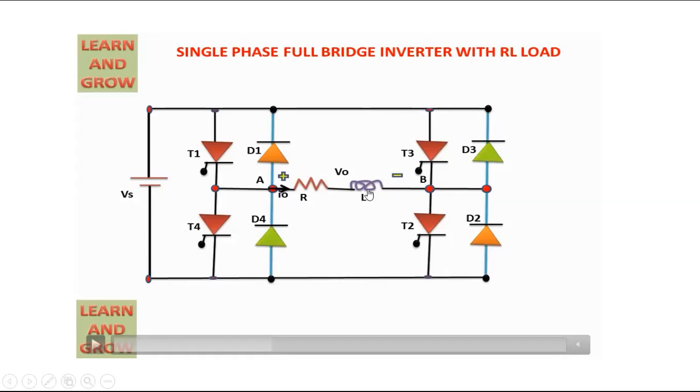So now when inductor de-energizes, the de-energizing current flows from L plus to D3 to source, and from source to D4 and from D4 to the L minus. So I hope you understood this one, as we have taken in choppers also. So inductive load, inductor releases the energy. That energy is passed to the diode D3 to the source to the D4 and D4 to the L minus.